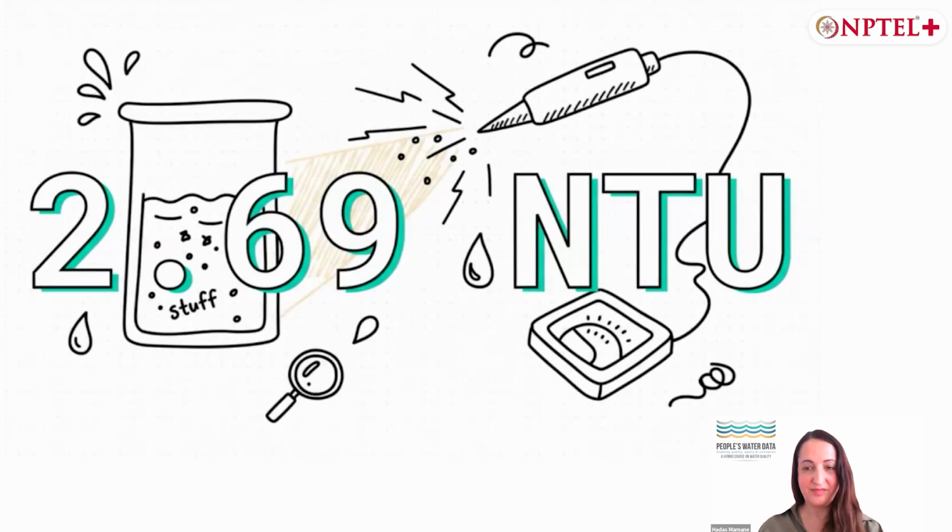And now, for our actual sample. The meter gives us a reading of 2.69 NTU. Okay, so it's not 0. That tells us right away there's something in there scattering the light. Just to give you some perspective, really good drinking water is usually below 1 NTU. A muddy river might be over 100. So 2.69 tells us something is definitely going on.